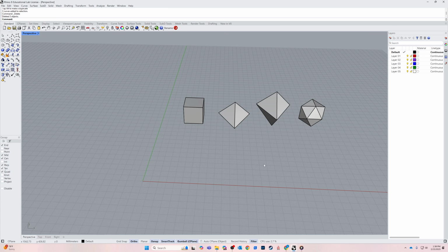So we're going to type polygon, and then we're going to do 5 inscribed, and then we're going to click, and I want it to be, there we go. So we're rotating it around. I want the bottom of it to be flat against the x-axis here. And size-wise, I don't know, it's kind of guesswork. So I'm going to go 5 quote for 5 inches, enter, click to get out.